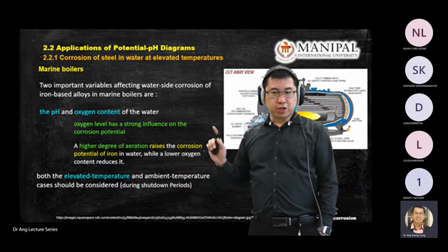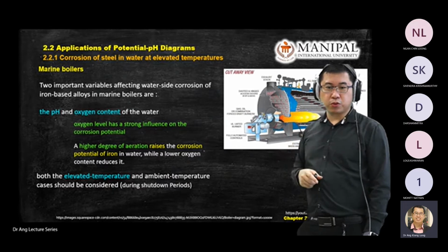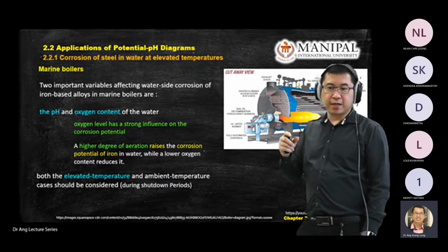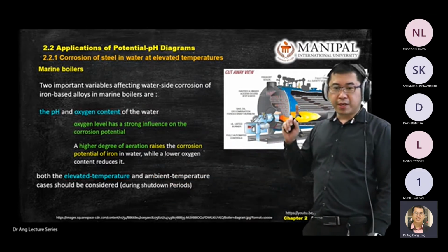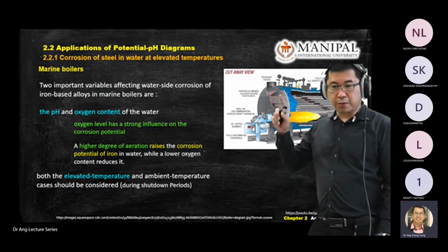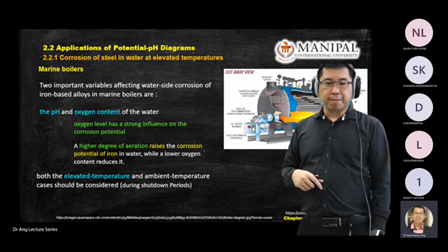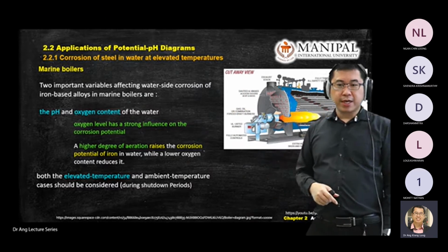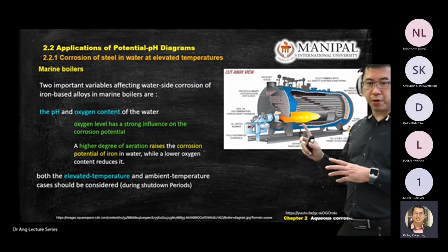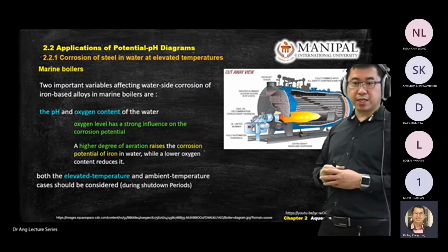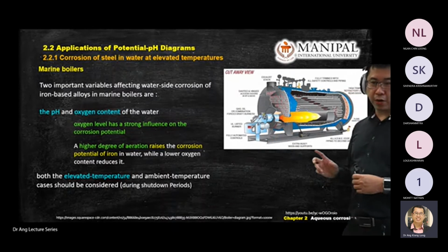And because the boiler is at a high temperature, it further contributes to the failure of the structure and the corrosion activity. Because of the high temperature of the boiler, the structure will change profile and properties, plus the effect of corrosion. Just a side note: when you activate the boiler, the temperature increases drastically. When you shut down the boiler, you also cannot shut it down straight away.